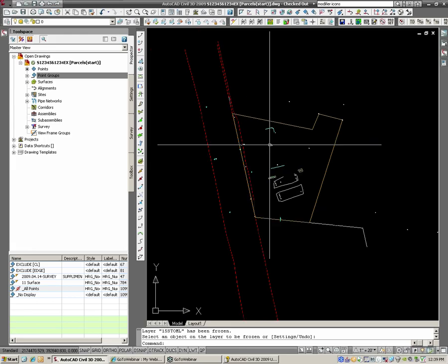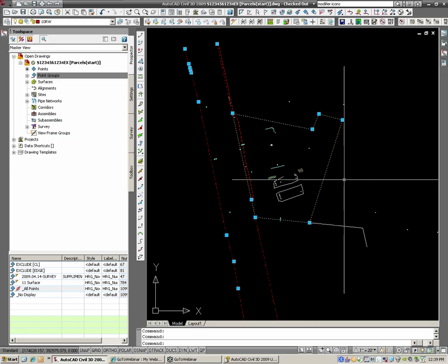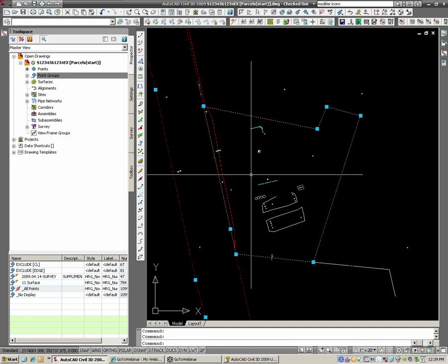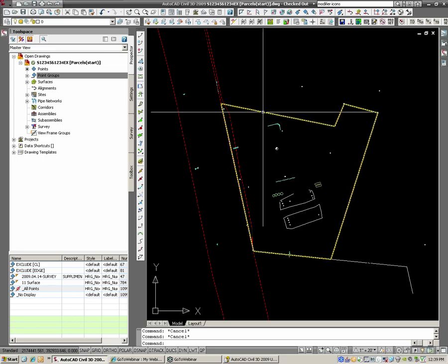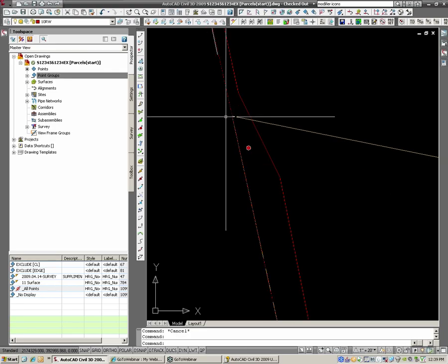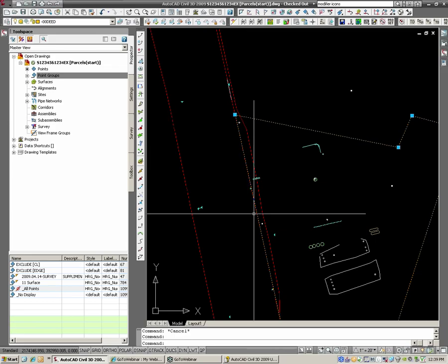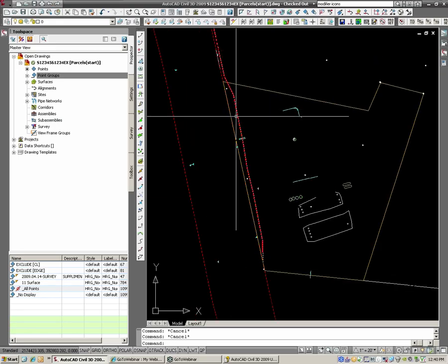All right, so we made our boundary determination, and what we have now is our two right-of-way lines, and then the deed. And somebody's determined where those exact corners need to be, and they gave me this information, and I'm just going to make some parcels out of this now. One crucial thing to keep in mind when making parcels, you cannot have overlapping data. So where we have this deed line, we don't want to have the parcel overlapping it. That's how Land Desktop worked. That is not how Civil 3D works, though. And it's something we covered in boot camp, but it's easy to forget.